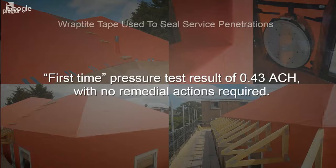Although the vapor control layer is not necessarily required as part of the air barrier system, they may still be needed to control moisture ingress, dependent on the precise specification of the construction. So we would always recommend an expert hydrothermal assessment be undertaken to verify this.